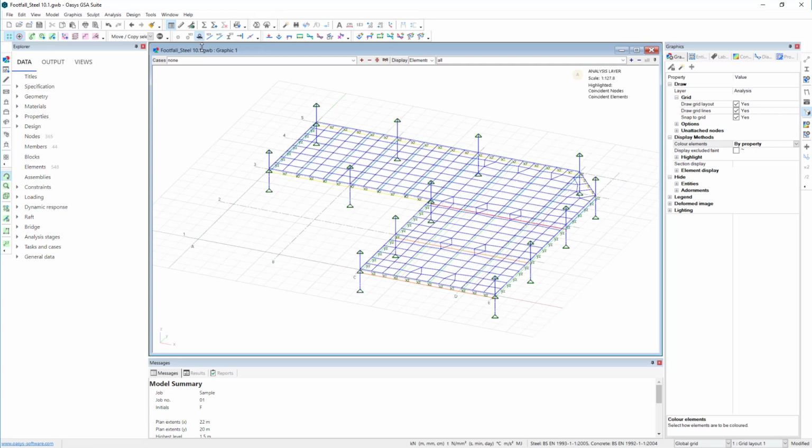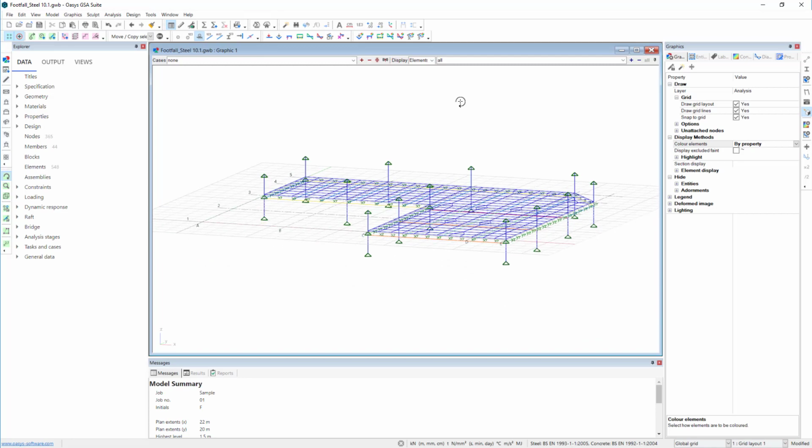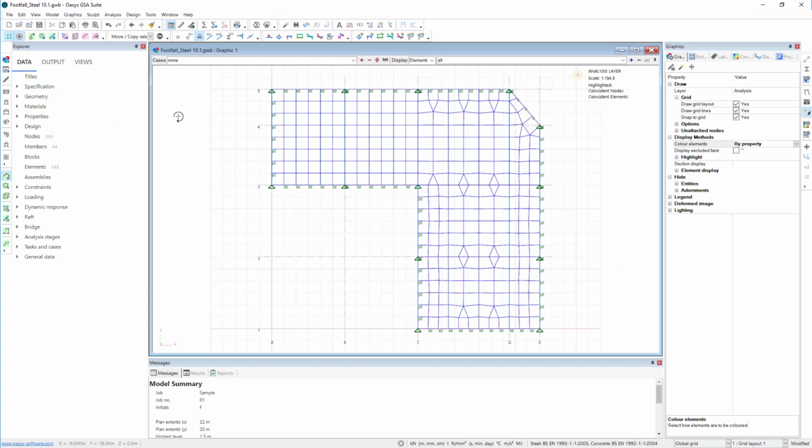And in terms of restraints, we see we've got the half height columns with pin ends. Also on the plan view, we see I've got edge restraints in the Z direction, but also in the Y or X direction as appropriate to represent the edge cladding.